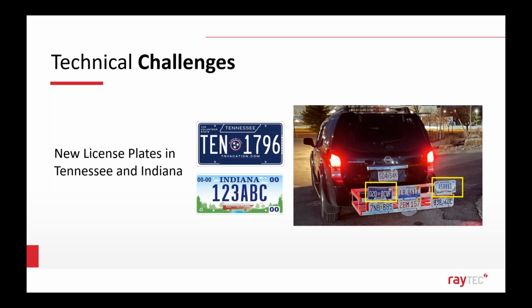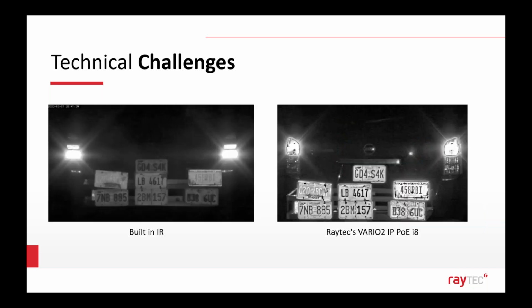And this change caused issues with the camera's ability to properly identify vehicles with the ANPR technology as they entered and exited the communities. Previous designs of these license plates were aluminium with a retroreflective material that was made using tiny glass beads that reflect light back towards its source, stamped with raised letters, and that was what created the contrast that allowed you to pick up the characters. But they changed this to a completely flat polymer/plastic plate with a blue background and white letters. So this is essentially what they were seeing on the left there.